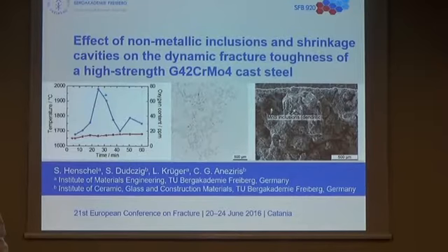There is no significant effect of the strain rate on the deformability, but as you can see, there's a slight increase of the deformability, and this is only attributed to the deformation heat, which is generated in the tensile test. There's no dependency on the radial position.